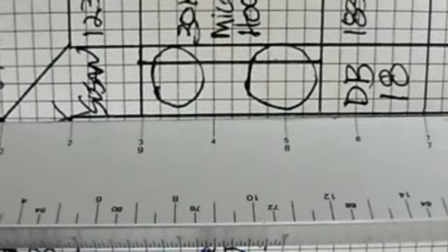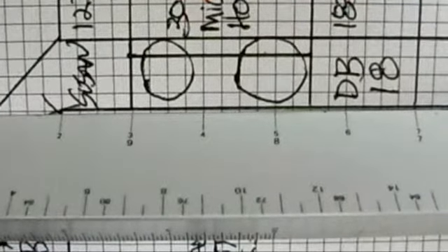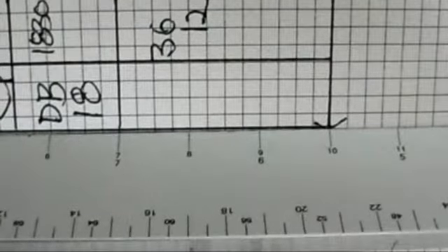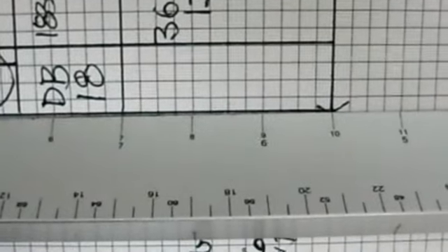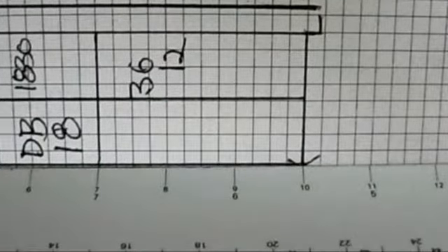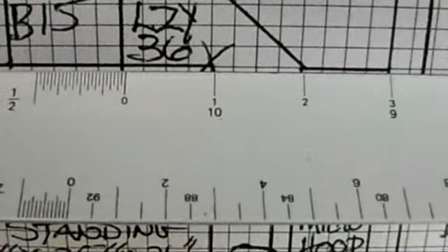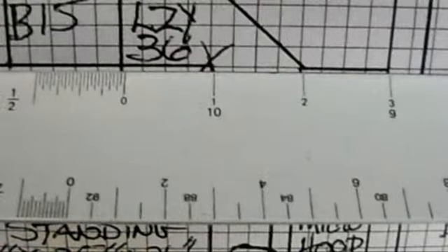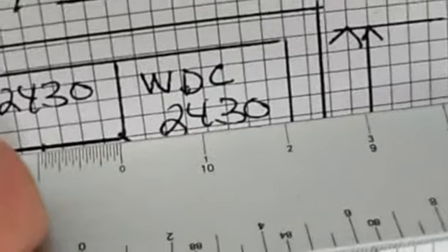So let's take a look at our plan. We drew a Lazy Susan. As you can see, that's 3 foot away from the corner with our 1/2-inch scale. And then you add that 30 inches, there's 66 inches, 5 foot plus the 2 squares, that's 66. Then our 18 inches, which brings us out to 7 foot from the corner, plus our 3-foot refrigerator. Success, it's 120 inches, and we have the 2-inch margin up above left. That's excellent. That's what you want. Coming out of the corner, you'll notice it's at 3 feet. Remember, you always want to work from the center of your windows out, and all this stuff will work perfect for you.